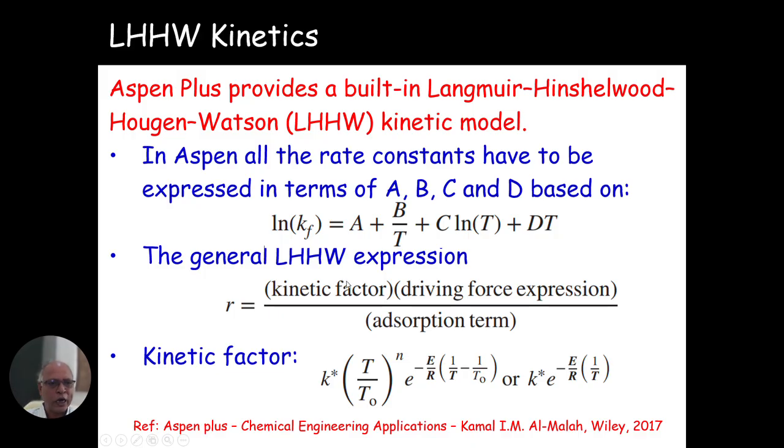There are a few other things that we need to look at. Remember one important factor: you will not be able to directly write the values of frequency factor and activation energy. You need to take the logarithms and then provide the values of A, B, C, D as per this equation. Normally when you use the rate constant in this form, obviously C and D will be 0.